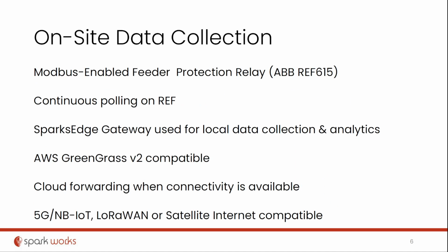So for the on-site data collection, we use the Modbus protocol, both for the weather devices that we have and also for the electrical circuit. In more detail, we use the ABB REF 615 feeder protection relay that can provide us with information about the energy production of the park at any given time.